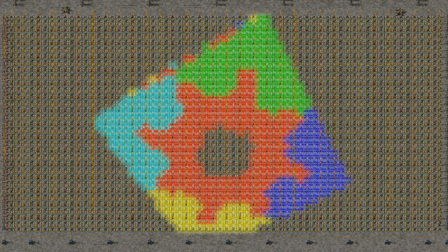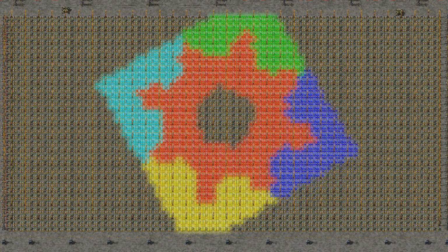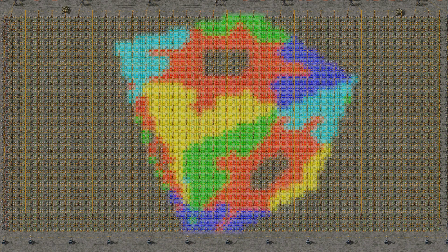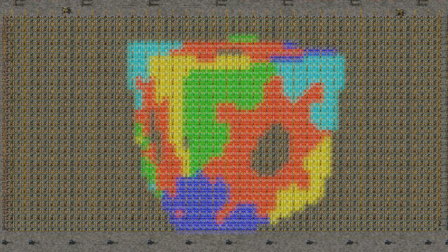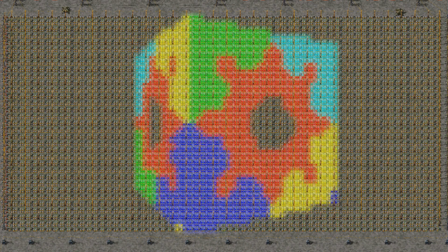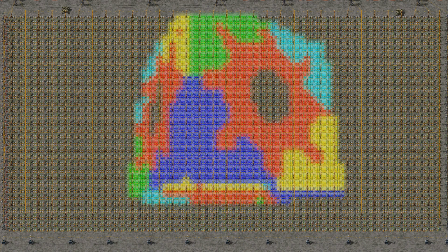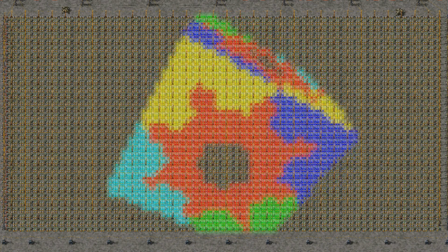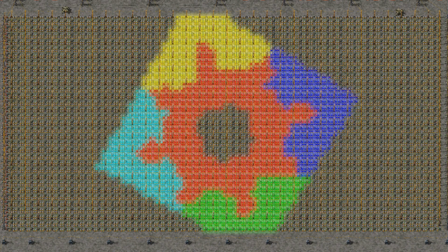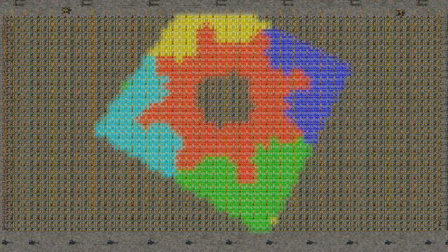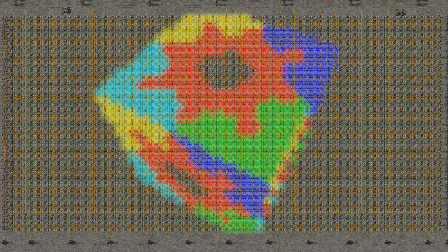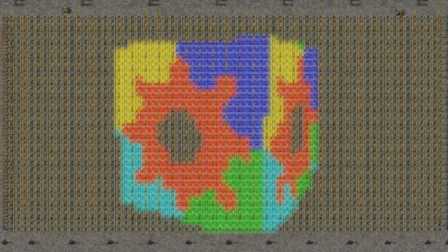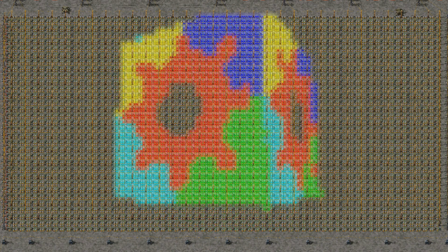The current display is relatively simple, but its limitations are too great, and I think it might be the main thing I need to improve to enable certain other features. Now, while the resolution isn't amazing, I think the bigger problem is color depth, or the lack of it. The current display has an effective bit depth of 3 bits, and that simply isn't sufficient for what I want to do. So I need to find a way to get higher bit depth. I have an idea for something that might be able to get me a 6-bit or 64-color screen, but we'll have to see if that idea pans out.